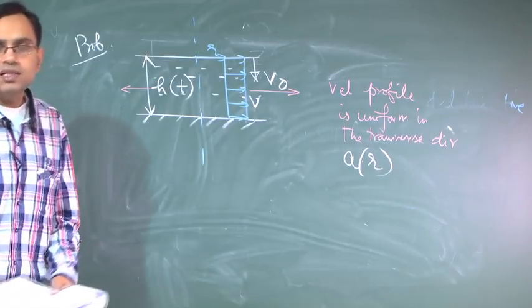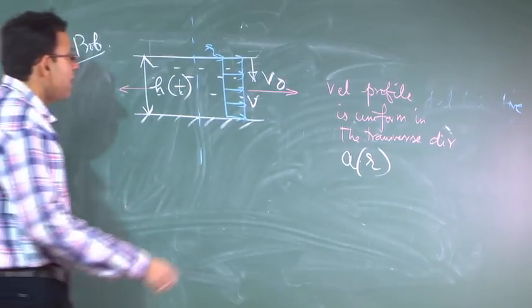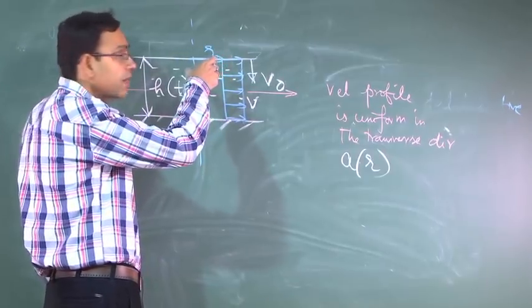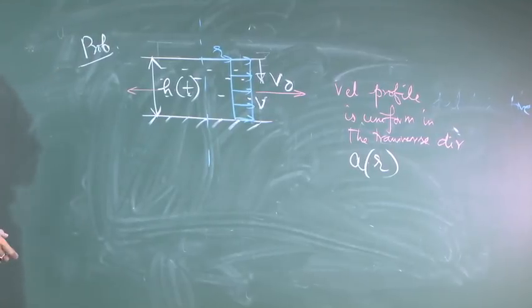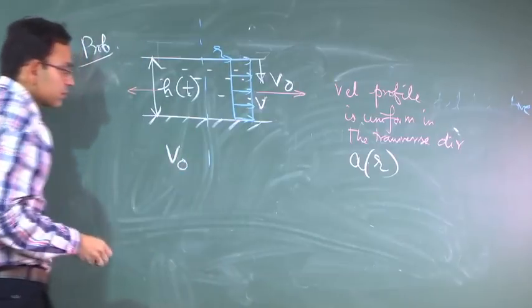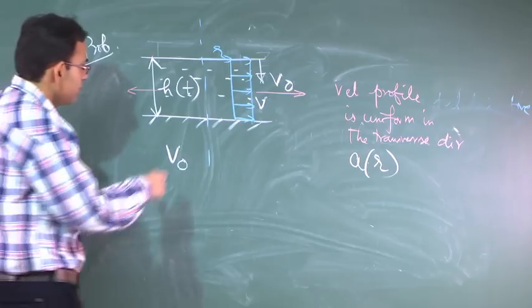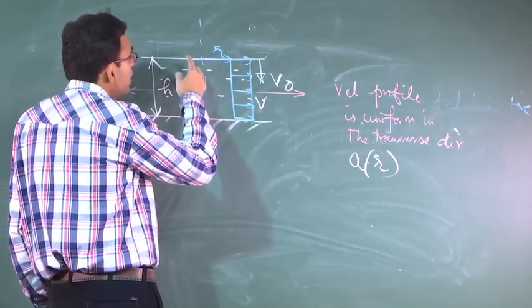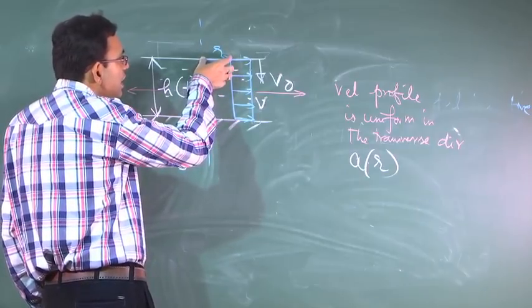So, what we are essentially doing is writing a simple mass balance to solve this problem. So, the mass balance is something like this. When this fluid comes down with a particular velocity, say V0, the volume flow rate corresponding to this is the velocity into the, let us consider a control volume which encompasses this radius r.